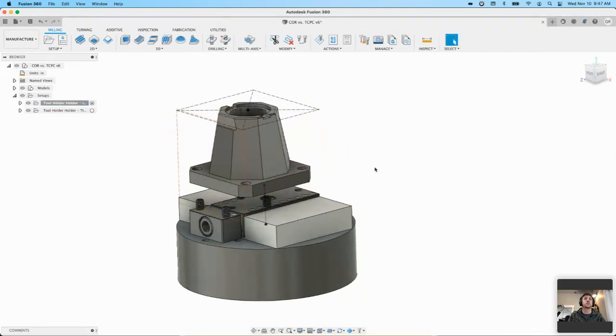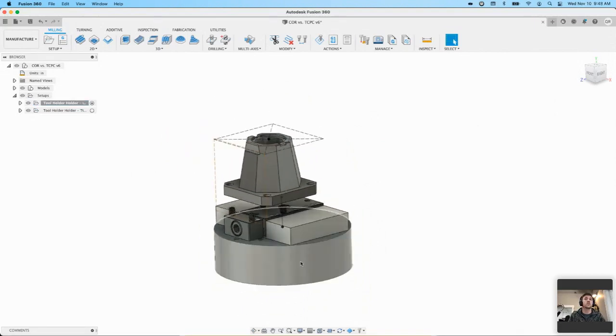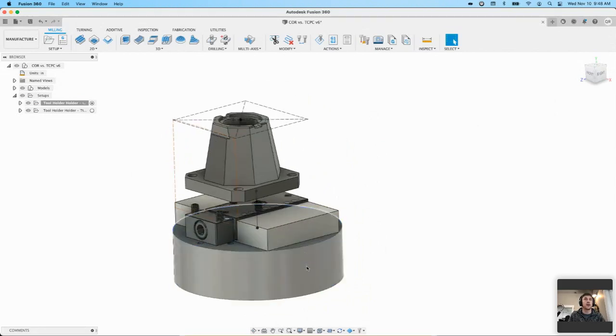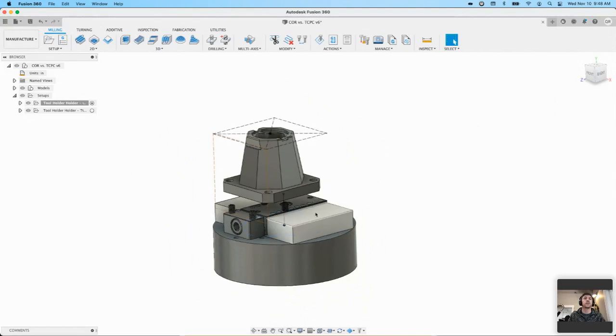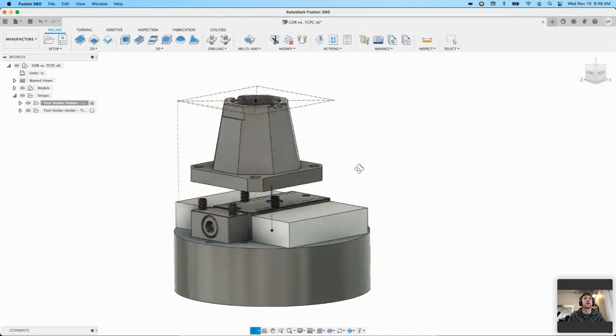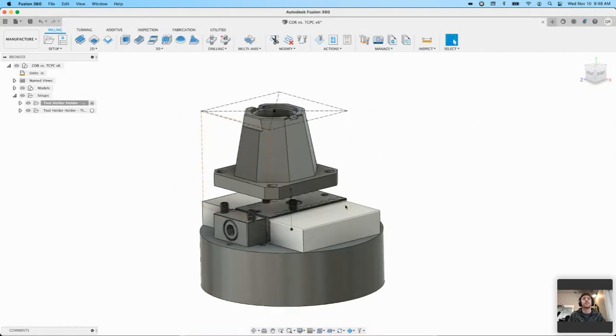So some of the challenges that came with that were we had to have access to a representation of the machine. In this case, our B table offset, our B table, as well as our fixturing, in this case our vise and vise adapter. So you had to have access to that from whatever fixturing manufacturer you used, and then bring that into your file with your part.